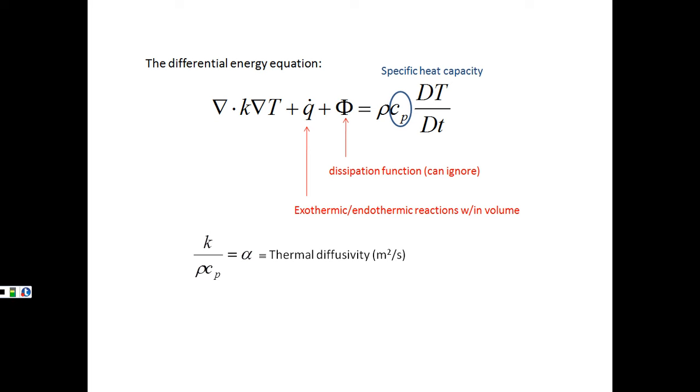So I do have a final form here. If we rewrite this into a form that's more familiar to you, we can consider this substantial derivative here. And we can say, okay, if we're ignoring the field effects so that our velocity isn't changing as a function of x, y, and z, and we just consider this change as a function of time, then that partial derivative, I'm kind of flipping this around, so we're going to the left-hand side here. Our partial derivative with respect to time is going to be on our left-hand side. Our alpha term is going to be like our diffusion coefficient. Then we've got our Laplacian of temperature. And then what we've done here is we've just taken the remainder of these parameters and we've divided through to make this one analogous